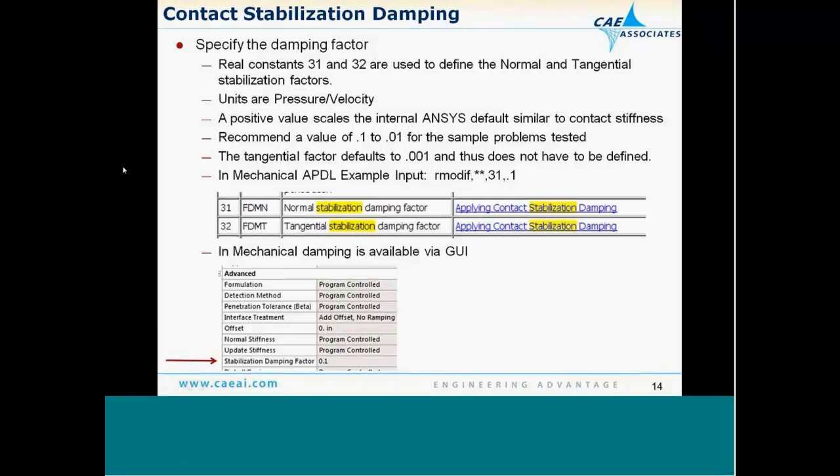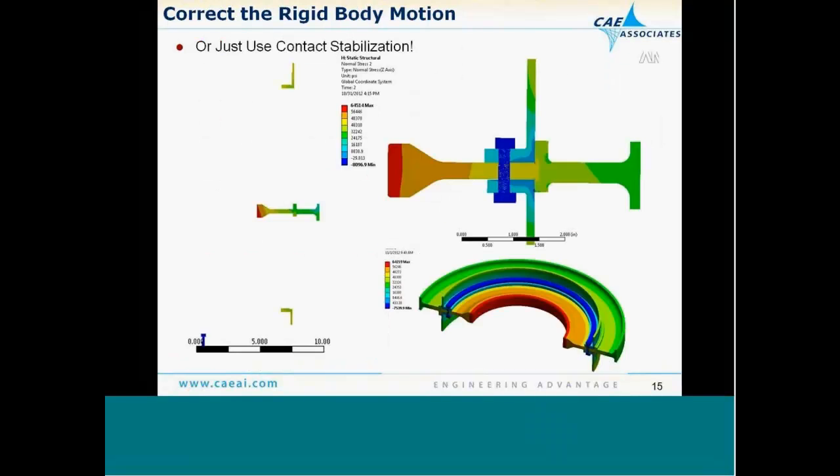And for many people, I'm sure, the answer was, well, I use all three of those methods. Which one do I use all the time? Well, it depends on the particular project and problem. All three of those I concur are typical solutions for overcoming non-convergence. But hopefully you'll find in some of your future problems that contact stabilization may be an avenue of overcoming non-convergence that works.